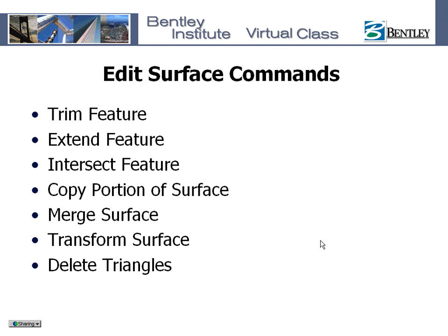Last, I'd like to go over delete triangles. This is the most used tool of the bunch. It's been around for a while. The delete triangle command removes surface data where no survey is present. This is helpful for exterior boundaries because every time you triangulate a surface after deleting triangles, the triangles will reestablish where you have deleted them.